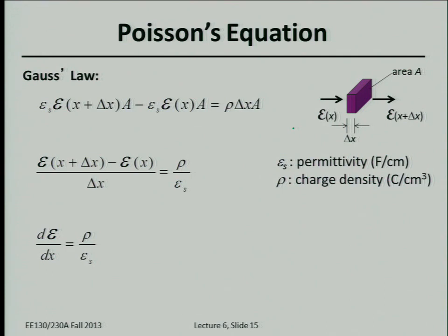And there's this ratio here, the permittivity, epsilon sub s. Different textbooks use different values. The relative permittivity of silicon, I'll just say it's roughly 12, but it's something like 11.8 or 11.9. I'll double check the textbook next time.